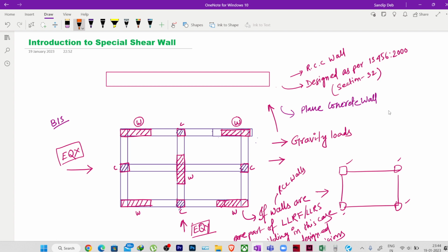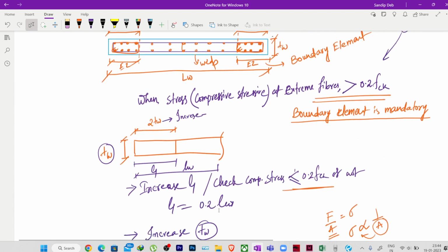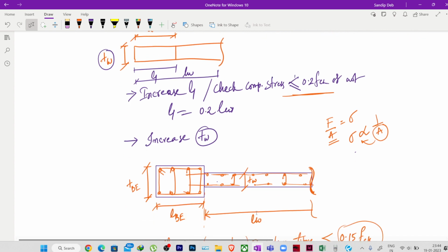So many people have this question, what we should do when we design a Mivan wall structure. So remember, Mivan wall is not a structural system. Mivan is just a formwork, aluminium formwork, which is not like the general formwork.